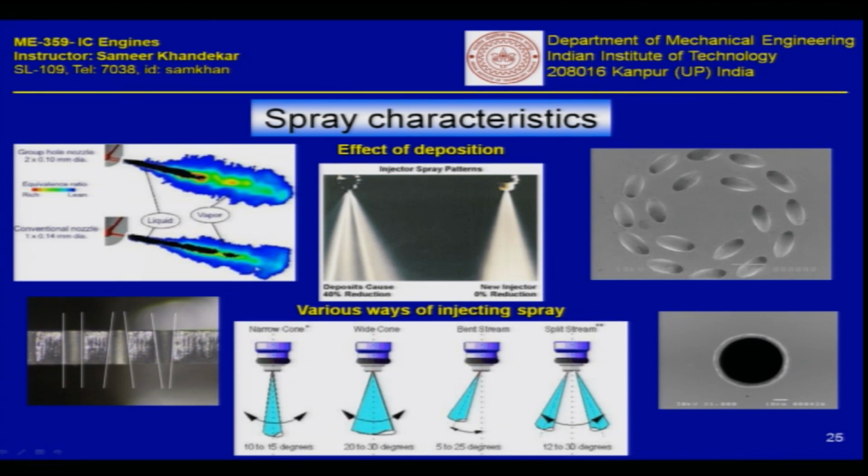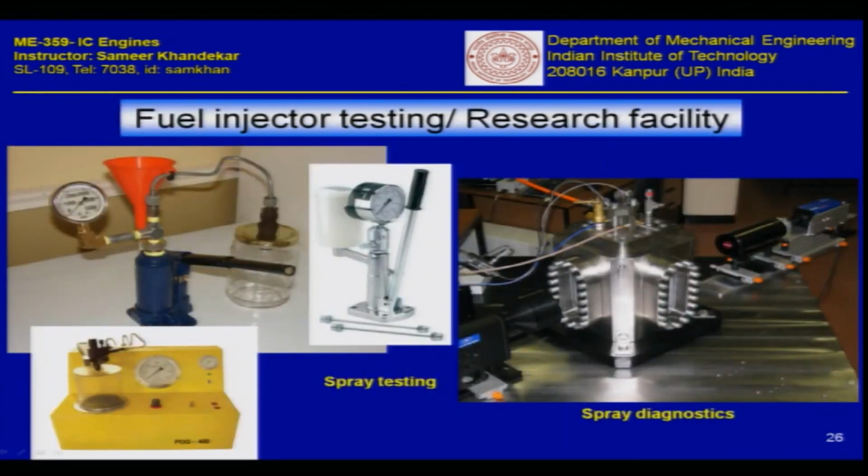and several researchers also study, for example, the spray characteristics, the cold flow characteristics, as well as the combustion characteristics, as well as computational fluid dynamic studies to get how exactly the combustion takes place, where is the kernel of combustion, how does the mixing take place, what is the level of turbulence around this spray, what is the Sauter mean diameter or the mean diameter of the particles which come out of this spray, what is the effect of the diameter of this hole, the inclination of this hole on the spray characteristics for example, and on the combustion efficiency and things like that.